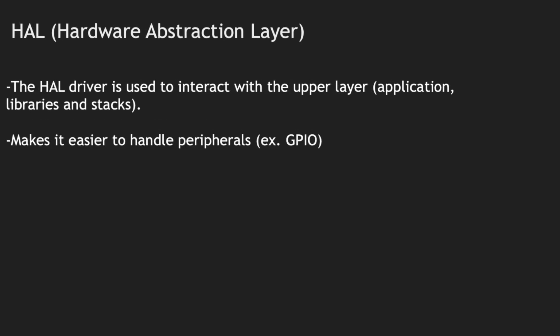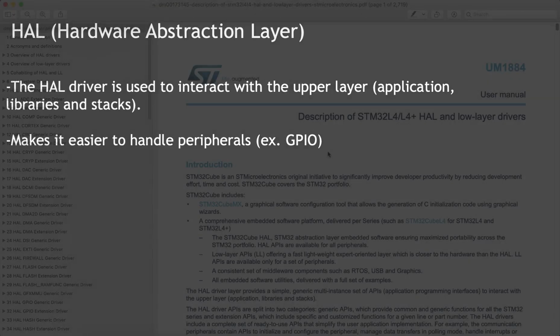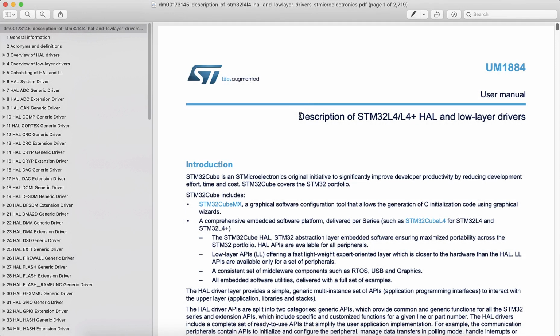To begin using peripheral devices and registers, ST uses something called the Hardware Abstraction Layer, or HAL. HAL is made by ST to standardize code throughout their boards and makes controlling peripherals, such as GPIOs, easier. To begin using this, I would recommend doing a quick online search for HAL documentation. You should be able to find this PDF on ST's website.